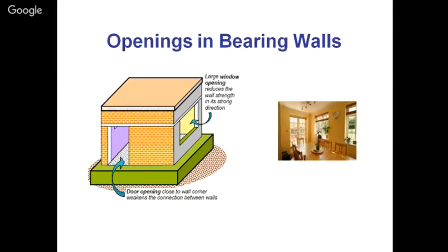But that particular slot which is cut due to a window in that particular wall, that part you are going to deduct from that moment of inertia, which is increasing the resistance of the building for that particular direction. As we calculate the moment of inertia for an I section, all civil engineering students might have done that, we reduce the part which is outside the flanges. It is the same thing, that we reduce the moment of inertia here. And the net moment of inertia we are having, that we use as the resistance towards the earthquake.